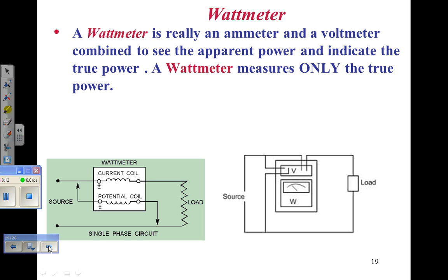It's 1,200 VAs, right? But it says right on it that it's a 1,000-watt motor. What does that mean? That's not it's only cranking out 1,000 watts of output. It doesn't say watts on the motor, it says horsepower, right? What if that's a 1 horsepower motor? That means it's only creating 746 watts of cranking force.